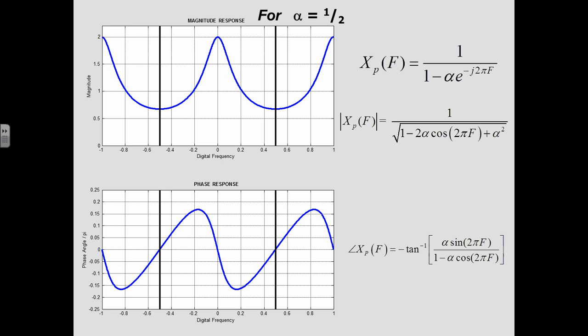So notice, as we expect with a discrete time Fourier transform, this is a function that's periodic. It repeats with every integer value of the digital frequency, which relates to the integer multiples of the sampling rate in analog frequency. So notice in the magnitude response, we get a peak at digital frequency 0. That peak is repeated again at digital frequency 1 and -1, and actually repeats so on at frequencies 2, 3, 4, and in the negative direction as well. Likewise, notice we have a periodic function in the phase response as well, repeating with the same period of repeat.